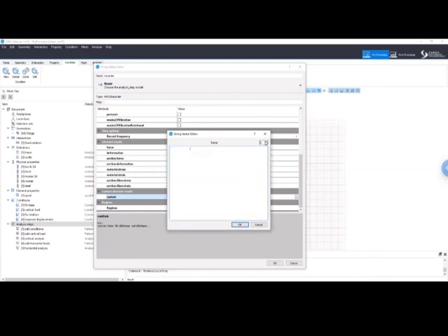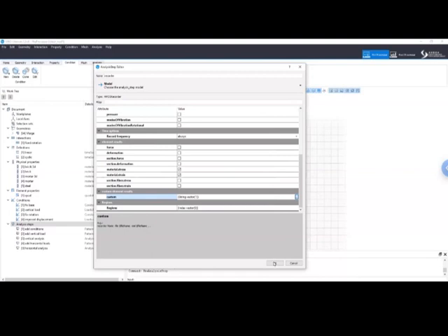Let me make room for just one. And I want to record the damage at every integration point. So it is sufficient to write material dot damage. Now damage is the name of the results. And before it I write material dot, because this means I want to record the damage variable on every integration point of these 2D elements, pretty much like material strain and material stress. So let me press OK and do OK.